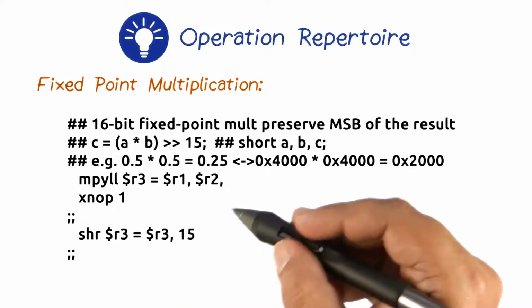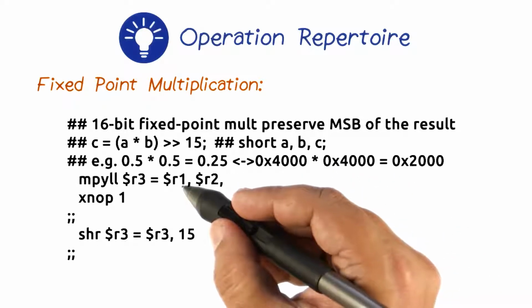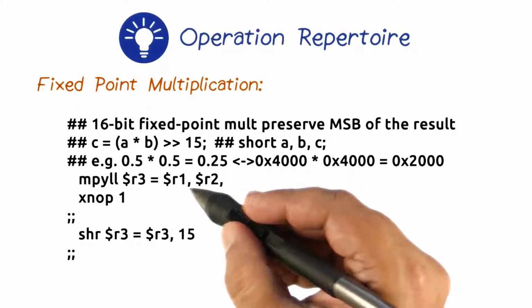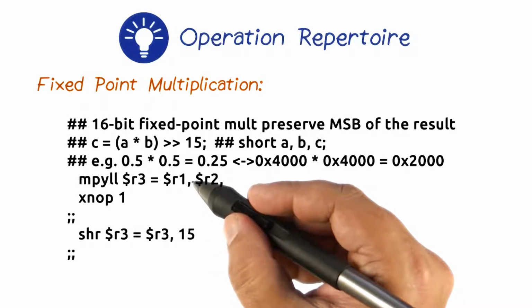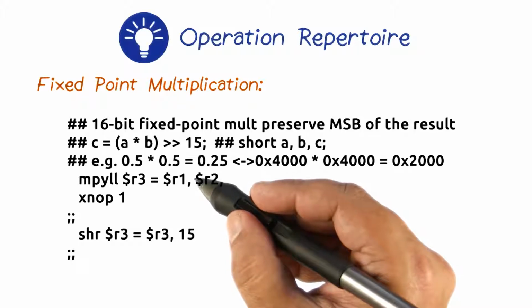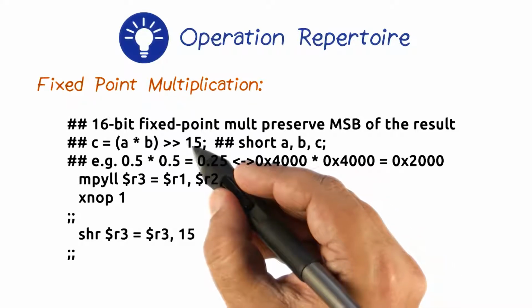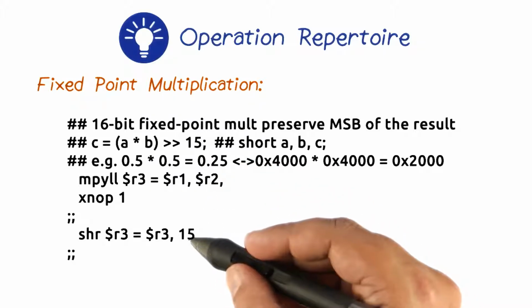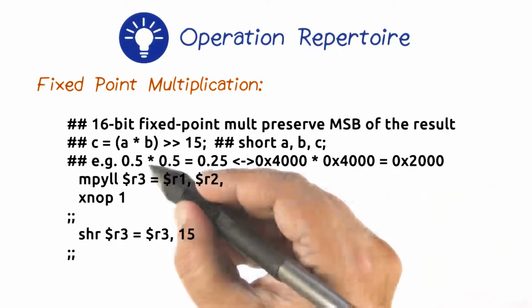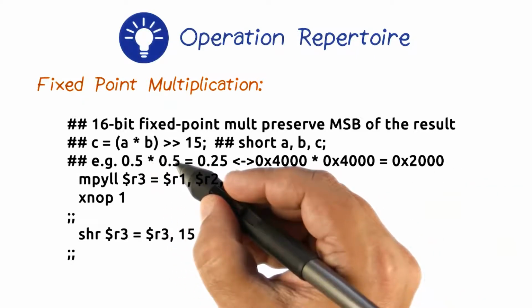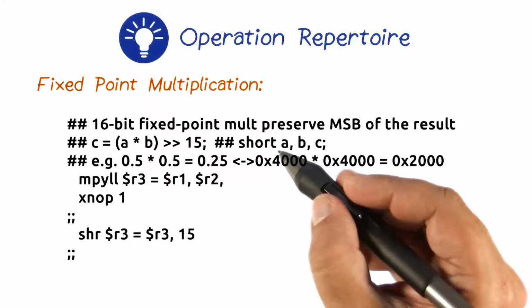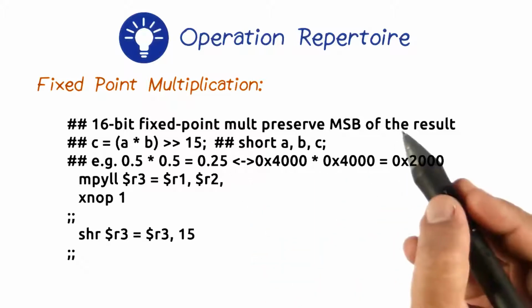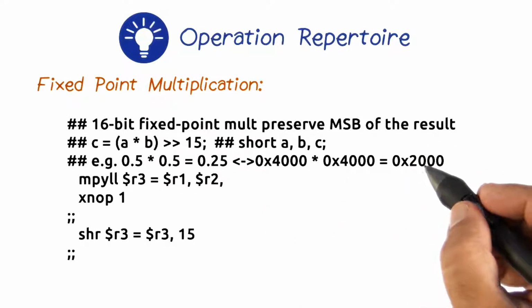So what happens during this process here is we start with the 16-bit representations in R1 and R2. We might generate the result, and the most significant bits might in fact reside in the carry and so on. And that is why we carry out a right shift here to bring that carry into the correct position so that we have the right result available. This is illustrated over here. If we have 0.5 multiplied by 0.5, it might generate 0.25 as the result, and then we carry out a right shift which is approximating that result to the desired value over here.